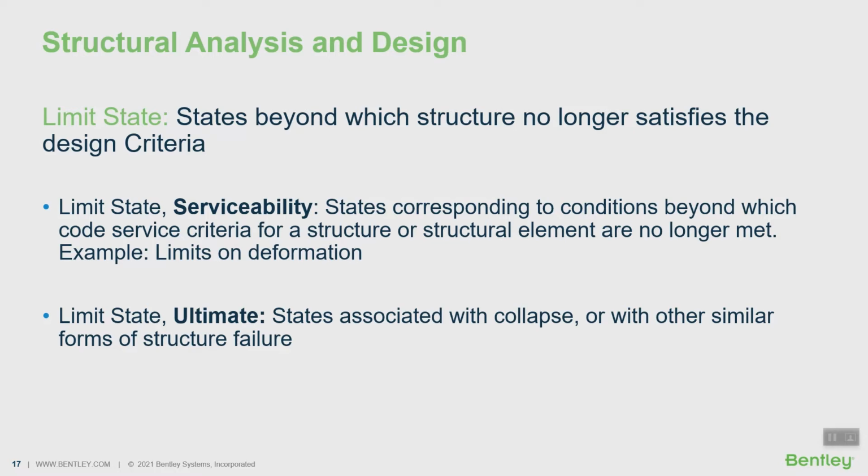There are certain requirements according to design codes that need to be met to make the design acceptable. These requirements are known as design criteria. And the state of a structure beyond which it no longer satisfies the design criteria is known as limit state. Beyond the serviceability limit state, service criteria of codes like limits on deformations are no longer met. Ultimate limit states, however, are associated with major structural failure, like collapse of the structure.